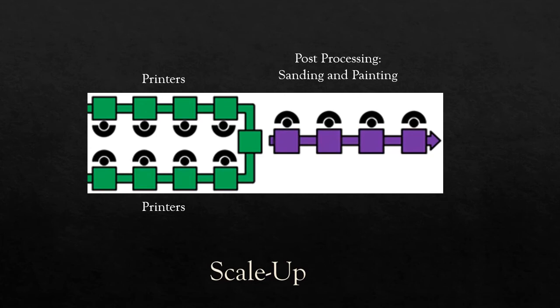For a hypothetical scale manufacturing, we think the most suitable layout would be having the printers placed in a U shape, followed by an I-shaped line. The U shape will facilitate travel from one printer to another. No skilled machinists are needed, so labor costs are lower. Only retooling and starting the printing process are required. After printing, the parts will be removed from the printer and then transferred to the I-shaped line to be post-processed. The post-processing methods include sanding and painting.